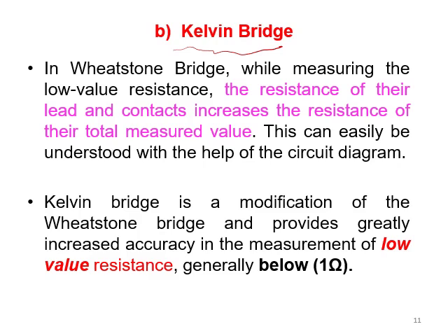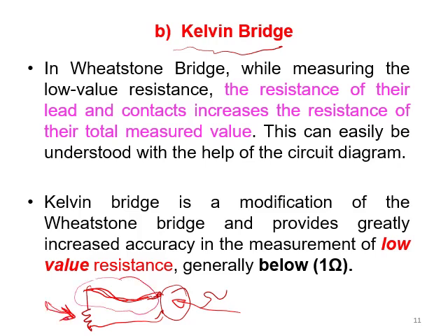What I mean here, if I have a resistor here, let's say I'm using the simple way, and I want to measure it by an ohm meter, for example, this is the ohm meter. There must be wires here to measure the resistance. So the wires are going to be connected to the terminals of the resistor. This is the wire, and this is the other wire. Now, the ohm meter here is not measuring the resistance of this resistor only. It's measuring the resistance of this resistor plus the resistance of the wires. That means the value I am measuring has error.